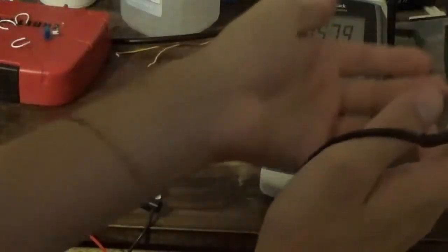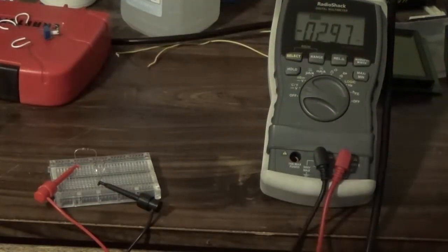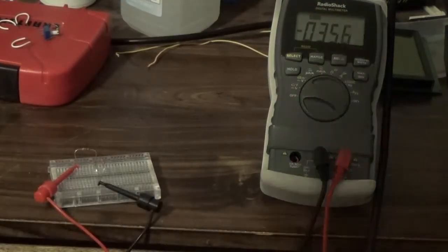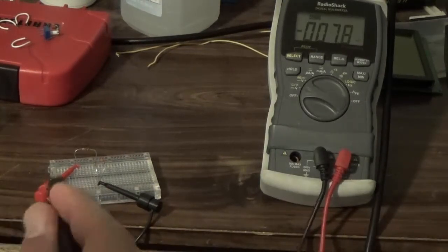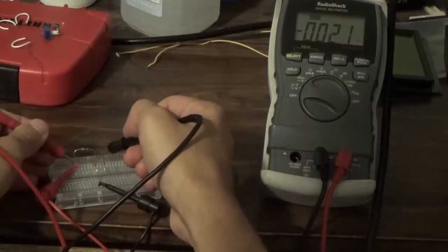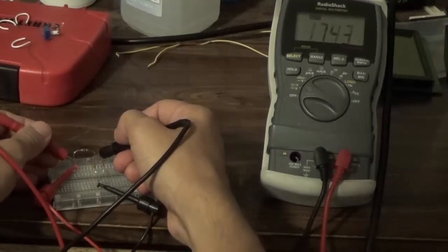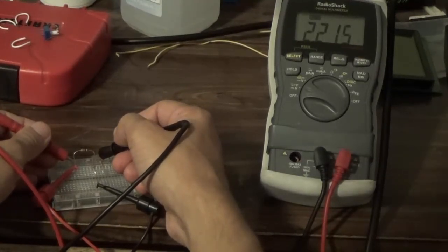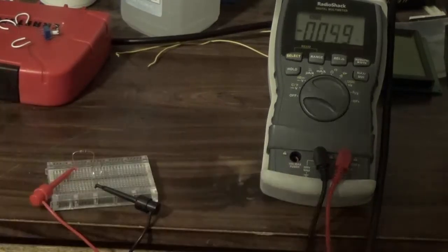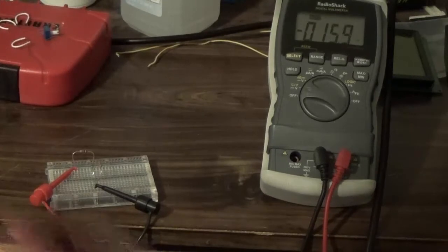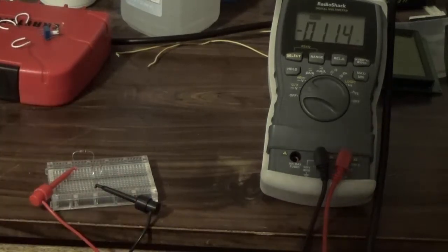So, like I said, pretty close to 5 volts, but there are tolerances in this world, and that's just what we're going to have to deal with. So we measured the voltage simply by taking this probe, putting it here, and putting it there. That's how you measure the voltage across a resistor, you put the 2 leads across, like that. But there's another parameter we have to measure. Remember, guys, we have to measure the current. In order to measure the current, it's a little different what you actually have to go through.